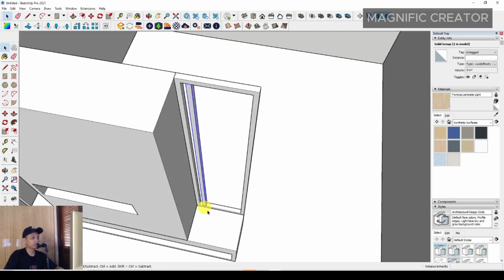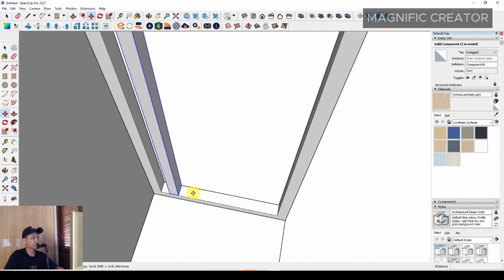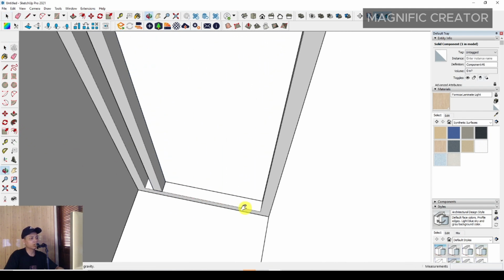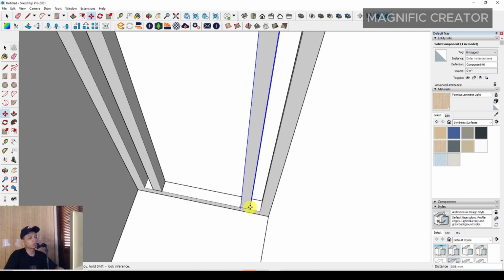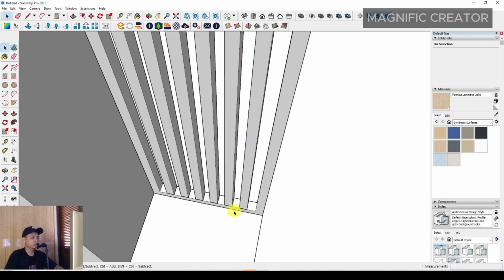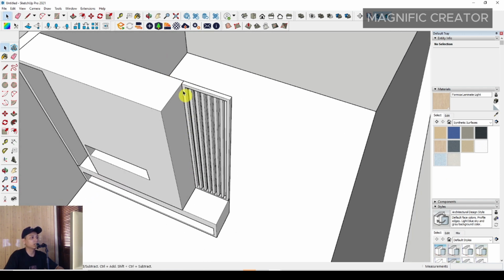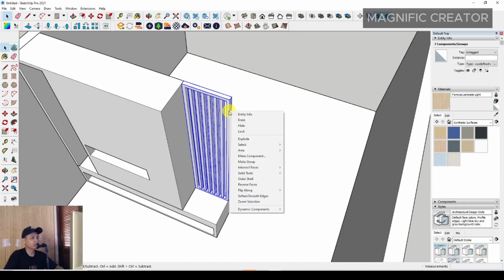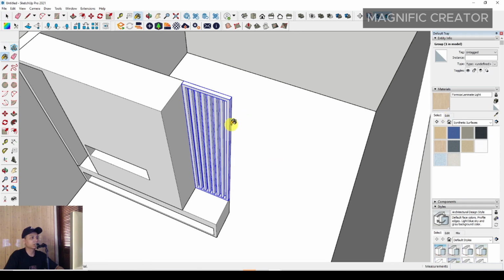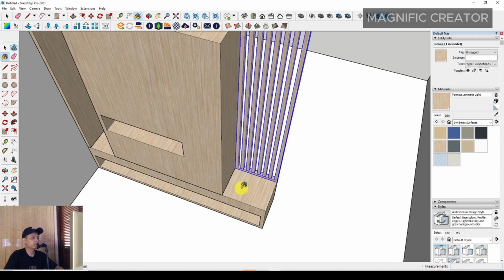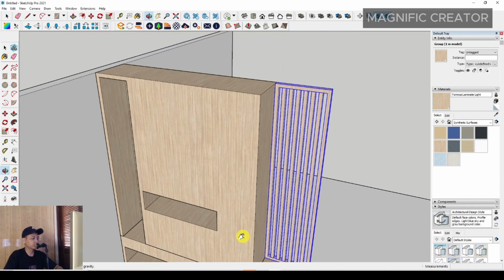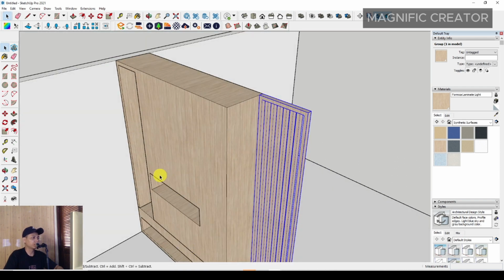Just create it. Then you have to press Move and Control, and you can set the end position as you want, and then you can set the count value by typing 5/, so you can see the automatic arrangement of this. Okay, and then you have to make it a group and just assign a material. You can assign all of this to be a single material anyway.